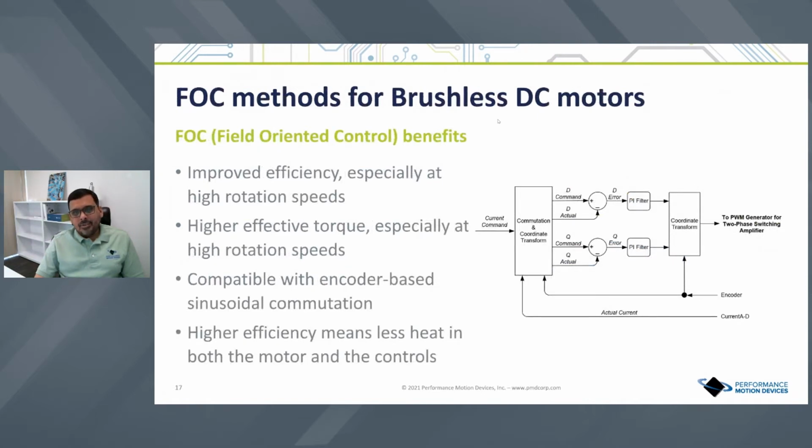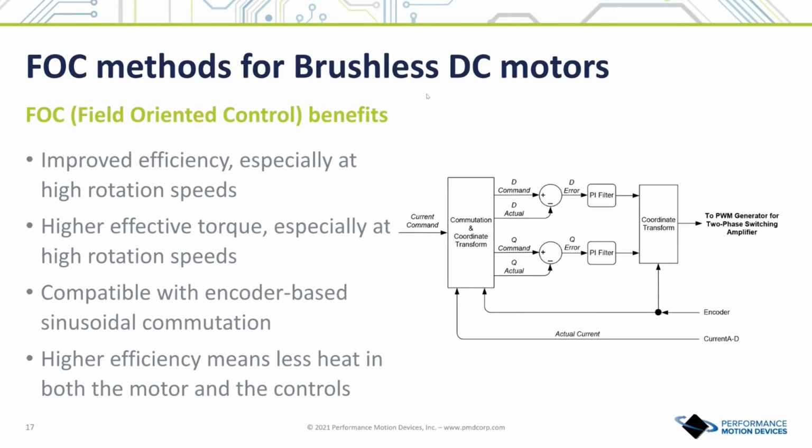And just a background on some of the advanced techniques that we do in the PMD products. One is this FOC, field-oriented control, where you get a closed loop current control. And this gives you a quick high-level overview of it. So you have the current feedback from sensors on leg current sensing, and then you apply the PI filters, and then you control the motor out of it. So this gets you operating at the right operating point and gets you higher efficiencies.